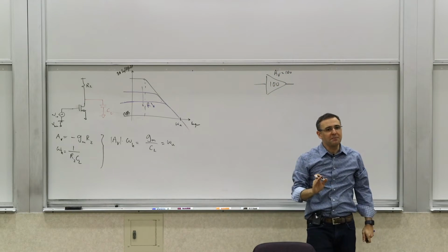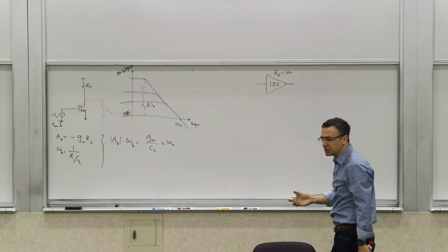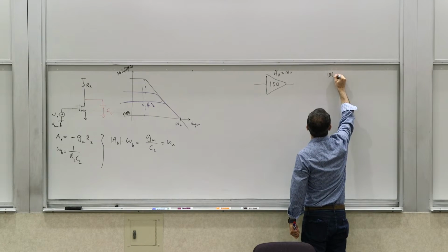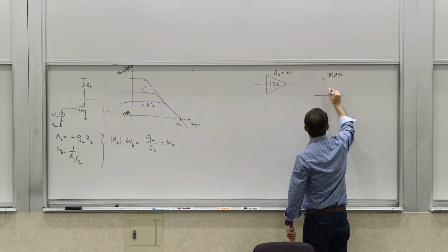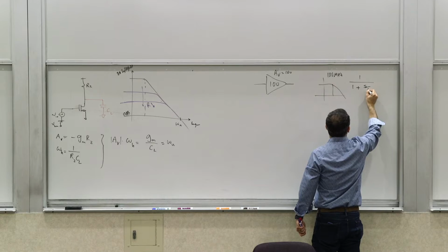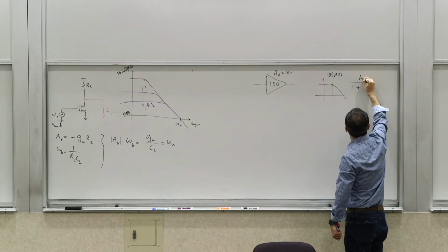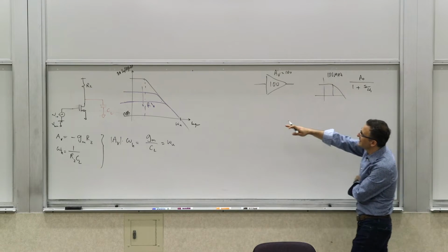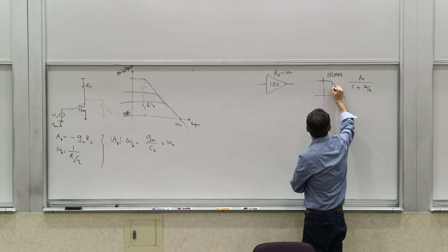And let's say your gain bandwidth product for the devices and the capacitors that you have gives you a bandwidth of, I don't know, just pick a number, let's say 100 megahertz. Let's say the response of the system was a first order system. In other words, the transfer function is A0 over 1 plus s over omega 1, where A0 is the gain. And let's say it follows this kind of gain bandwidth product trade-off, made out of these amplifiers that we talked about.